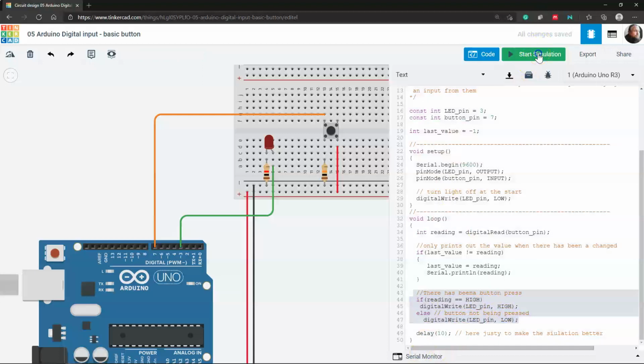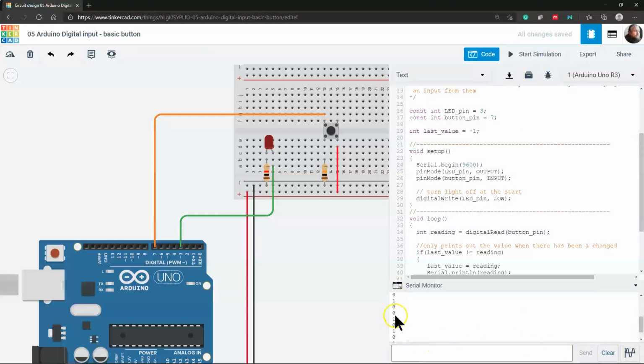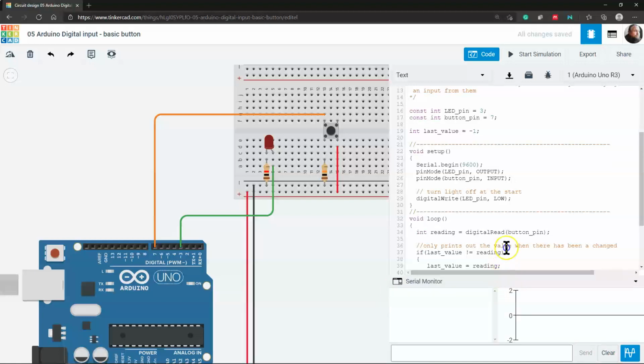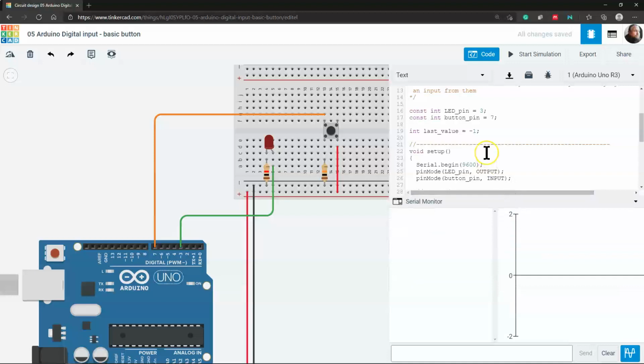Now if I stop the simulator, I just want to open up the serial monitor so we can check the output for that. We have some extra things here already and I'm just going to clear it. And I'm just going to open up the serial plotter for fun just to see what it's going to do with this, because I didn't exactly design the output of the code to be meant for it, but I am curious. So we will start up the simulation, and you can see here beginning with it got a 0, which is that first read that it got off of there is a low, and so it's not going to output anything else because there hasn't been a change in the actual value.